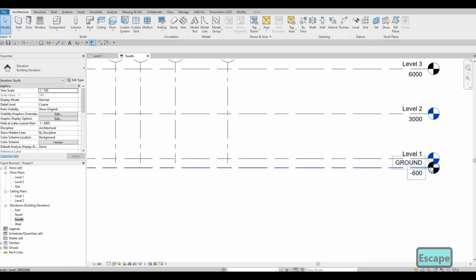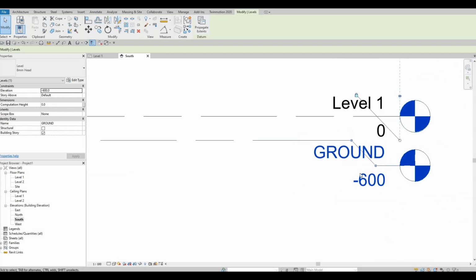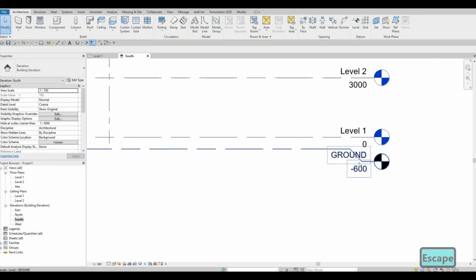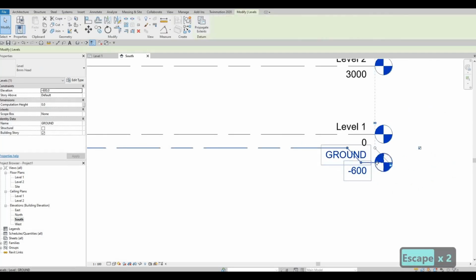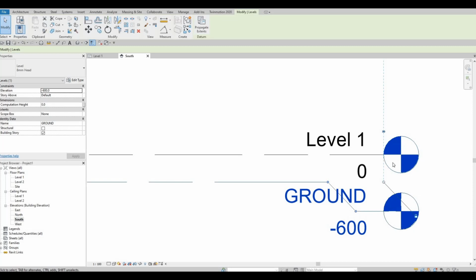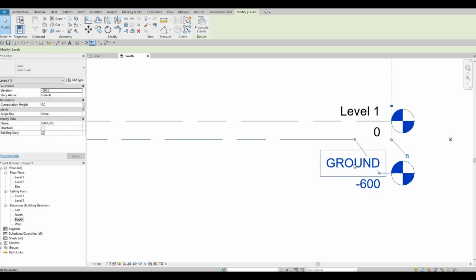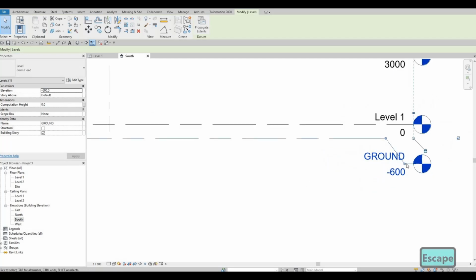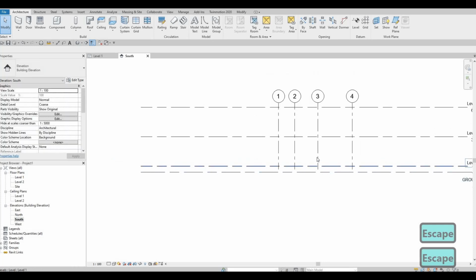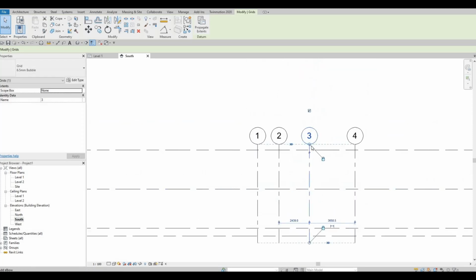You can also break this, so select this and look for the break line. So add elbow. From there, you'll be able to see it perfectly. So now you can extend this, similar to the grid line. Once you extend this, it will extend all. But here you'll be able to extend the elbow like that. And then here, I'm just going to put it all the way down like that. And then I'm going to extend this one at the top as well.